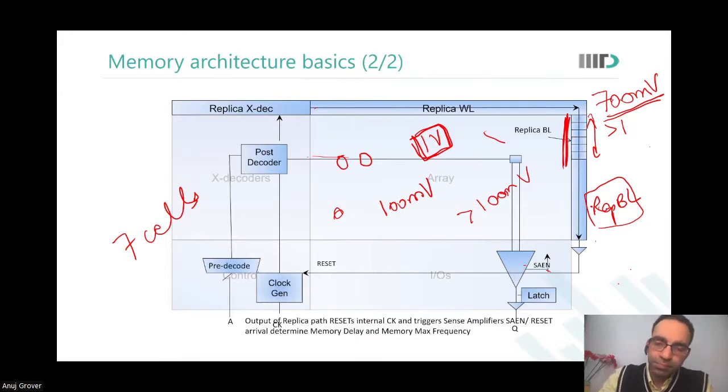Sir, how will you replicate this bit cell exactly? I didn't understand how you are doing that. I just repeat the cell. Sir, just repeating the cell means, layout wise I do understand that we can place the same layout over there. But this cell which we have should be the worst case, right? And we'll be replicating the same cell all over my memory cell, right? So how does that make a difference actually? It doesn't. The replica bit cell is supposed to look exactly like the real bit cell.